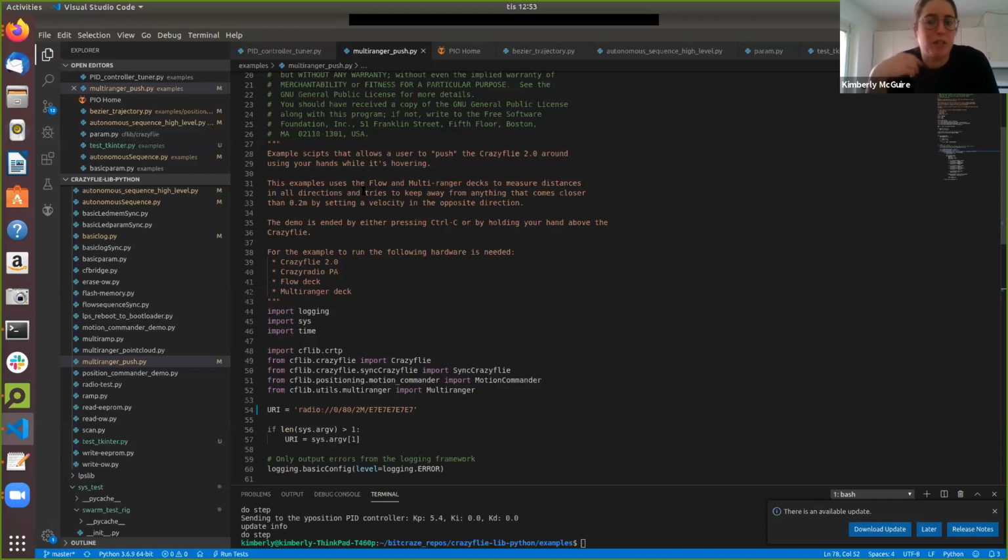The thing is how much you want to communicate with that Crazyradio. Because if you want to communicate a lot, 3 for sure. If you just want to give it a sign of okay, start your sequence now, or start taking off now, and let the Crazyflie do everything by itself and only give it some commands every once in a while, then you don't need to communicate with it that much. And then you can pretty much have 9 per Crazyradio.